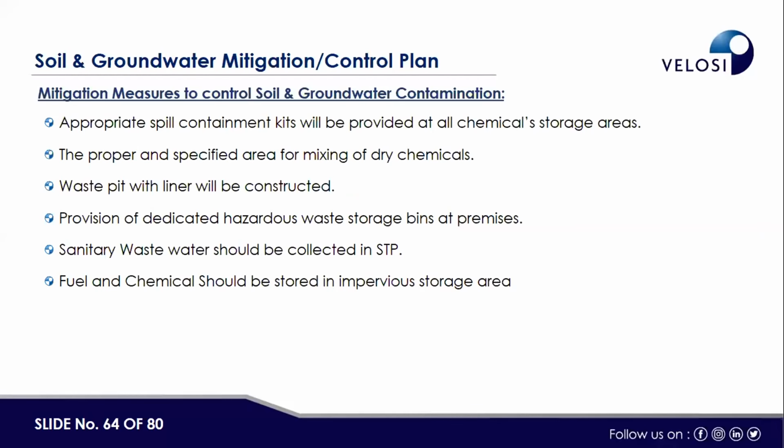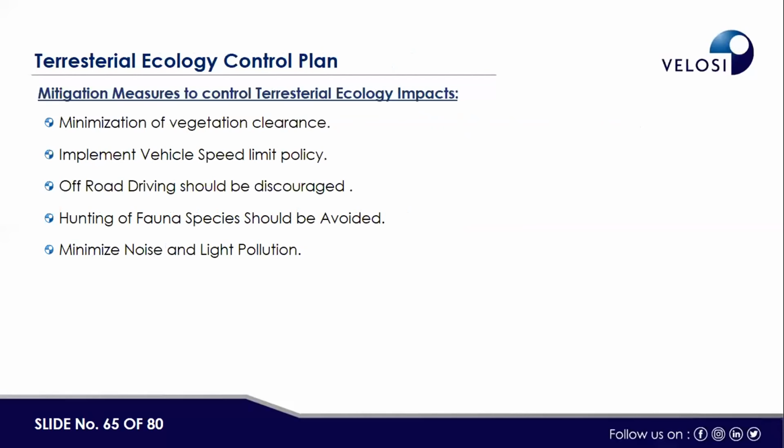Appropriate spill containment kits, a proper and specified area for mixing of any chemical, waste pit with liner, provision of dedicated hazardous waste storage bins. Sanitary wastewater should be collected in an STP, sewage treatment plant. The fuel and the chemical should be stored in an impervious storage area.